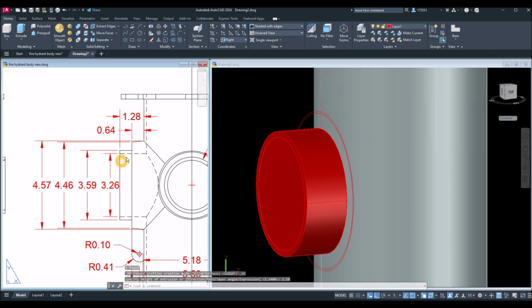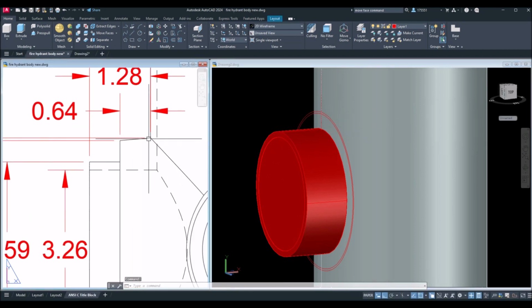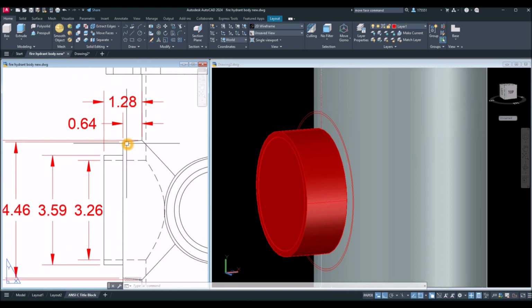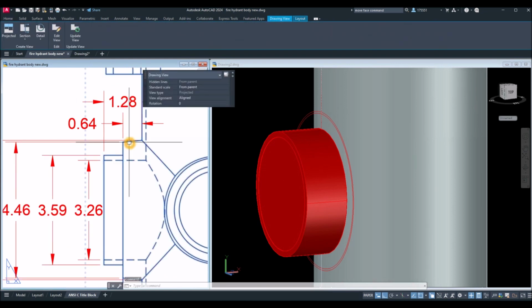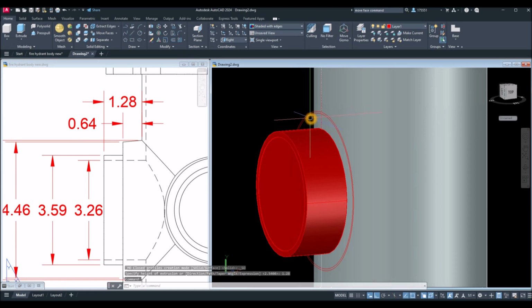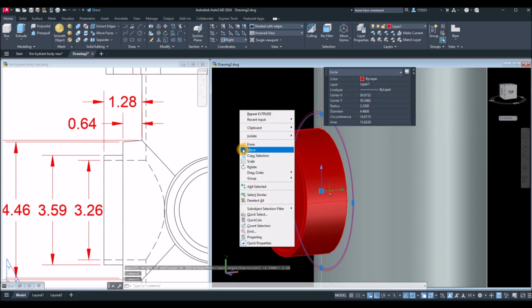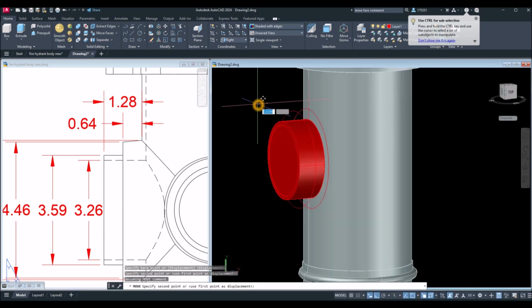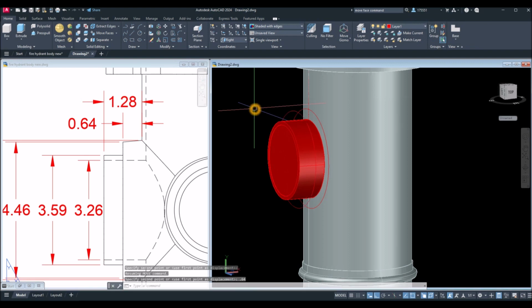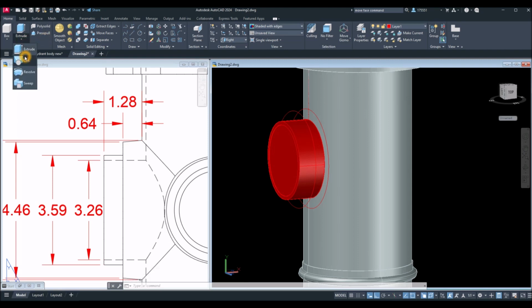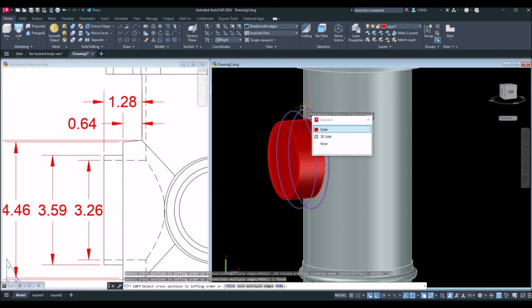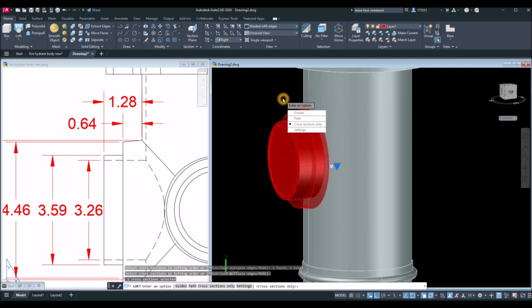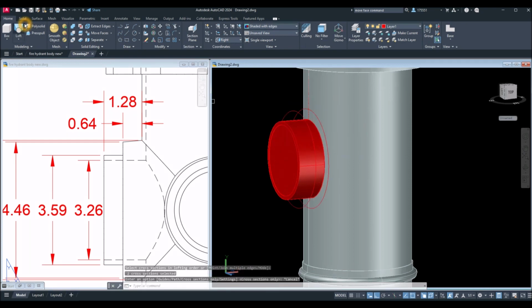And these 2, as you can see here, the extrusion is angled. So what I'm going to do, because the angle is not given, is use loft command. So move this smaller one, move, click anywhere on the screen, and follow that x-axis and enter 0.64. And now I'm going to use loft command inside the modeling panel. So click this one and this one. And enter again. Oops, loft.